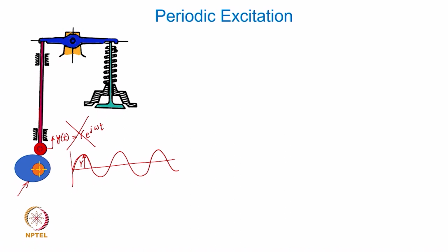For example, all the rotating machinery by default will always have unbalance as a sort of a residual unbalance exciting the dynamic system. So, the harmonic excitation function in terms of the force acting on any rotating equipment is definitely going to be there. So, harmonic excitation case is definitely very important and practically relevant as well.